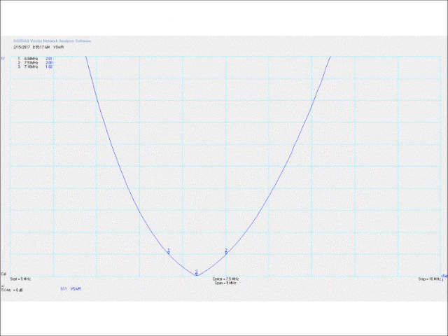How many of you have seen an SWR curve before? You got a little antenna analyzer? They all look like this. So right here at the bottom, where that number 3 is, I think it is, that is an SWR of 1 to 1. Everybody wants that. This next line is when the SWR is 2 to 1. And typically when you're measuring an antenna, you want to know what the 2 to 1 bandwidth is.